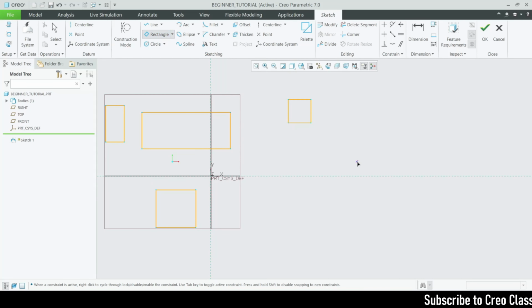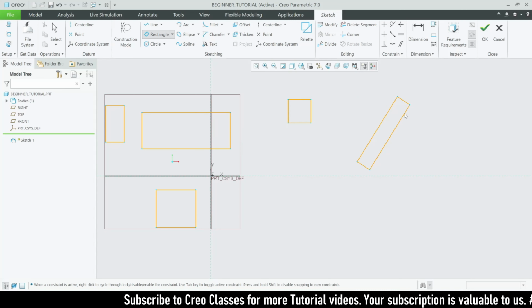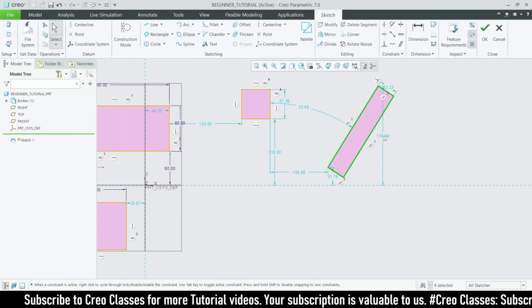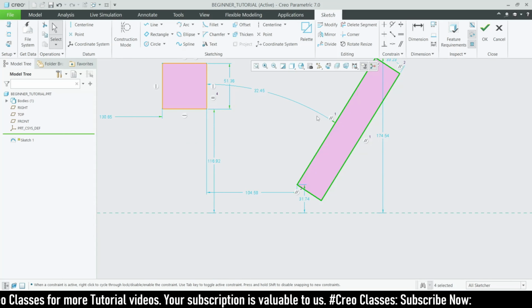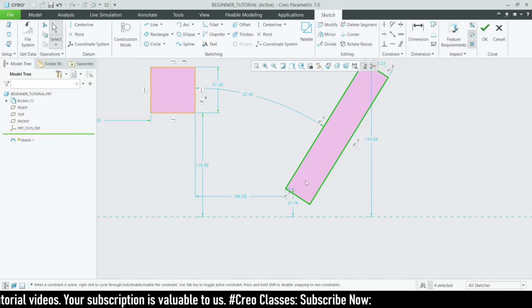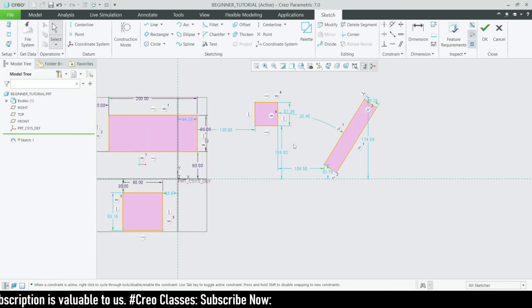And slanted rectangle is nothing but at first you need to draw a line like this. You have to select the first point and the second point, and then you can drag like this. Okay. This is how you will create this slanted rectangle. And then while pressing the escape key, you can also add the angle value, like at which angle the rectangle should be bent, and the distance, breadth, height, and everything can be edited by you.